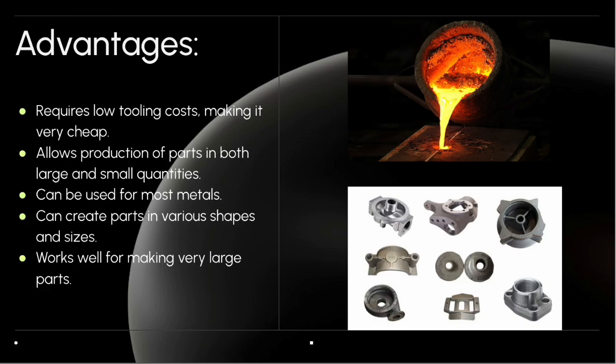You place that piece into a mold, which is then covered in green sand. Green sand is a mixture of sand, clay, and water. Once the part is removed from the newly created mold, it leaves behind a cavity in the shape of the part. When we pour hot metal into that cavity, the metal is then given time to cool.